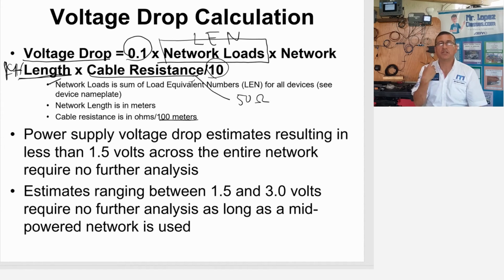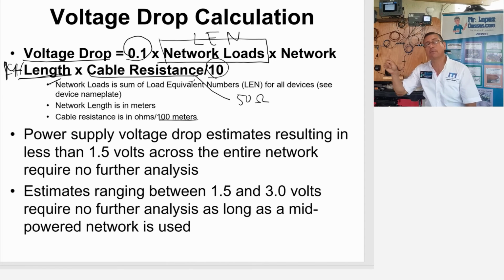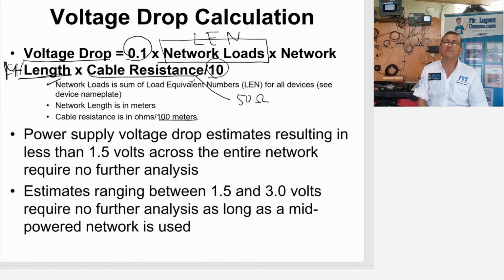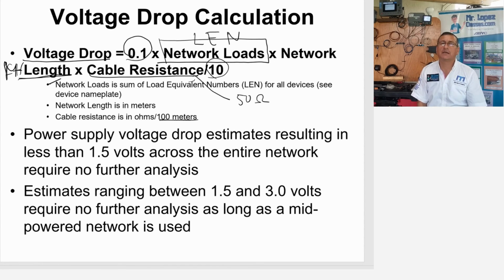Probably, according with my experience, in the majority of the cases, there are more than 50 equipments connected. Somebody installed an additional equipment a couple of weeks ago and passed the limit of 50 equipments. This is one possibility. Another possibility is the total cumulative drop lines is more than 78 meters. You need to check the distance of each equipment to the backbone, add it, and verify. Oh, I have 83. Yeah, this is the attenuation. You have excessive drop distance.